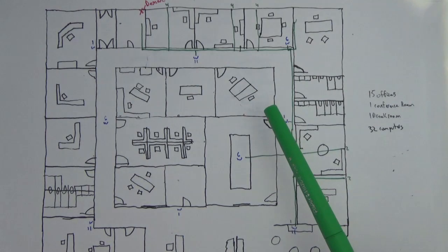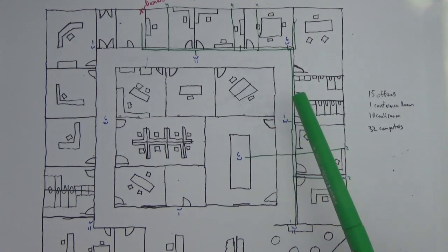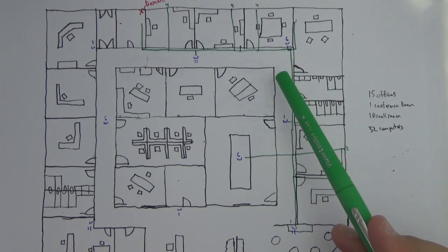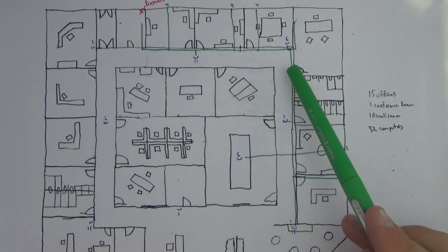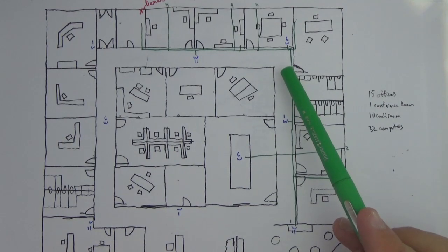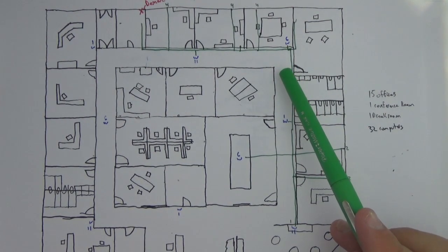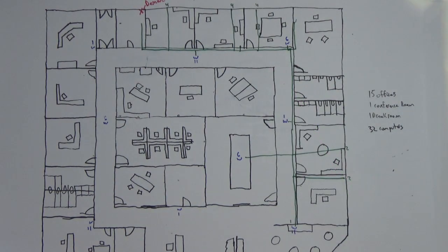We want to keep an eye out for other interference sources. We do want to make sure that we are protecting those cables, so either running them in a pipe or running them along a cable track or cable tray, something along those lines. Now, once we get into the offices, simply for aesthetic purposes, we're going to want to put those either in wall if we can, or inside of a cable track on the wall. We don't necessarily want wires coming up through the floor or dangling down from the ceiling that are just bare wires.